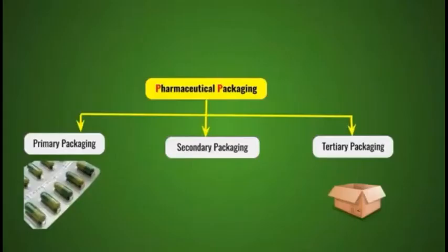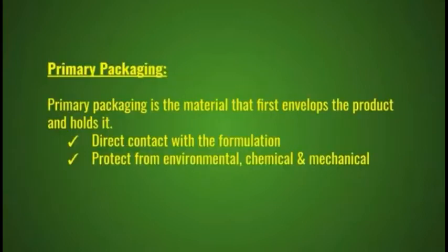And the ingredients commonly found in a rubber closure are rubber and vulcanizing agents like sulfur. Sulfur acts as a vulcanizing agent, the accelerator is 2-mercaptobenzothiazole, the activator is zinc oxide, the extended filler is carbon black or limestone, and there are also reinforcing fillers, softeners or plasticizers, and antioxidants and pigments.